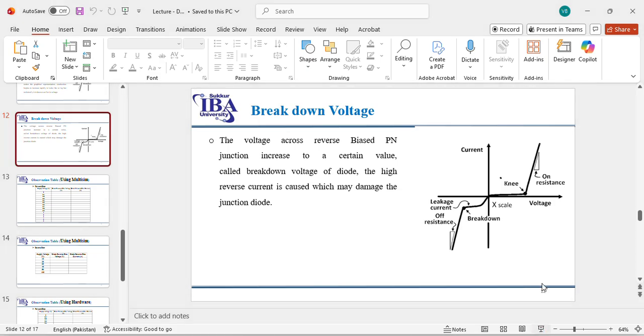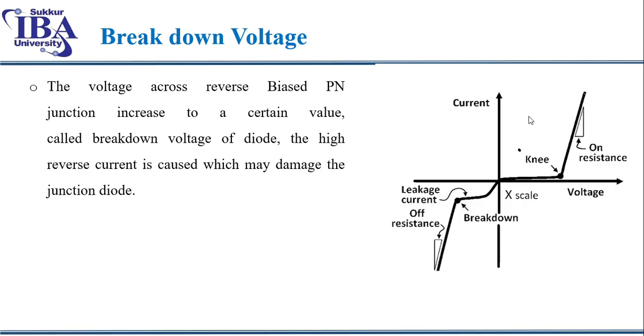A curve like this. So we will get this part of the curve that is in the forward bias. Till 0.7 volt, there is a very minute amount of current. After 0.7 volt, there is a constant increase in the current with a slight change in the voltage.